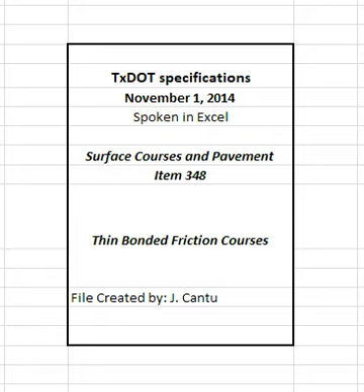4.4.2.2.2 Hamburg wheel and overlay testing. At the contractor's request, the department will perform the Hamburg wheel test on the laboratory mixture in accordance with Tex-242-F to verify compliance with the Hamburg wheel test requirement in Table 8. The department will perform the overlay test in accordance with Tex-248-F to verify compliance with the overlay test requirements in Table 8. The engineer will be allowed 10 working days to provide the contractor with Hamburg wheel and overlay test results on the laboratory mixture design.